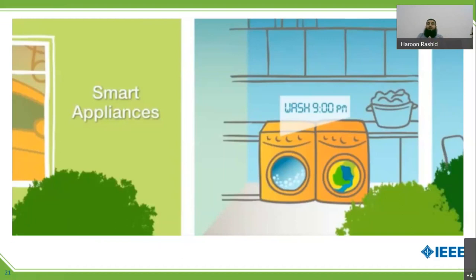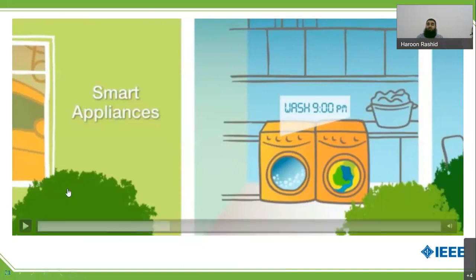So in order to balance the load, they have come up with this idea of off-peak and peak charges. They do not encourage people to use their appliances in the peak hours. So you use most of the appliances which can be done in the off-peak hours so that you pay less and the electricity shortfall doesn't happen in the peak hours. That is how the smart appliances in smart homes contribute to smart grid technologies.